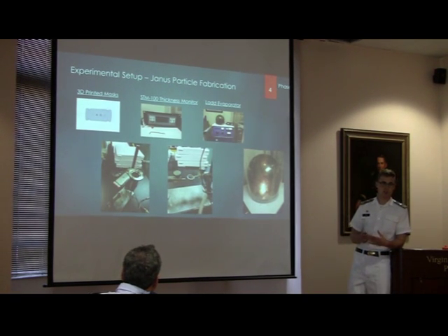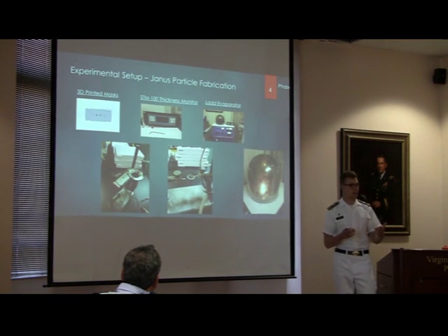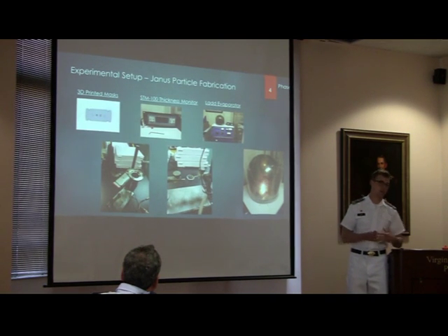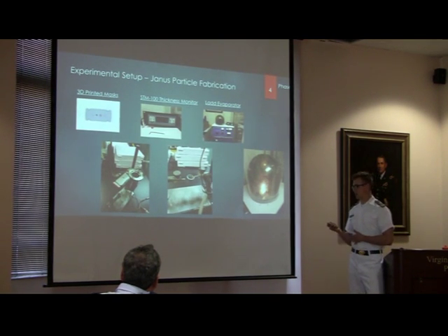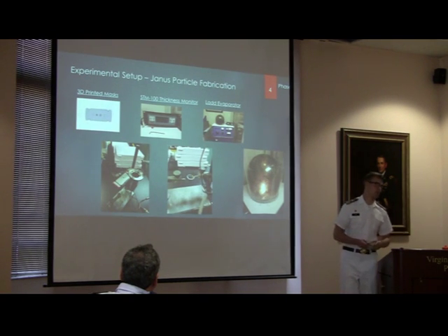This crystal has a known vibration rate, and when the nickel ends up on it, it changes the vibration rate due to the weight. So this black box would calculate that and say, all right, if the weight has changed this much, then you must have a thickness coating of 140 nanometers, for instance.